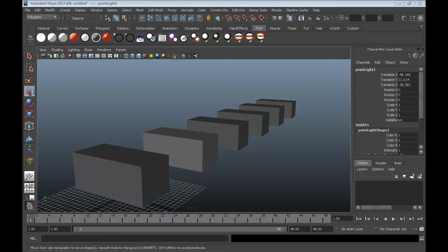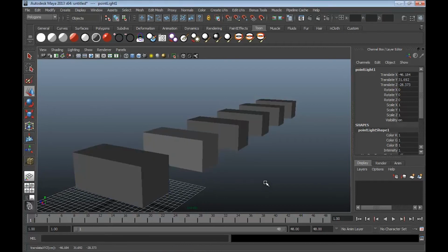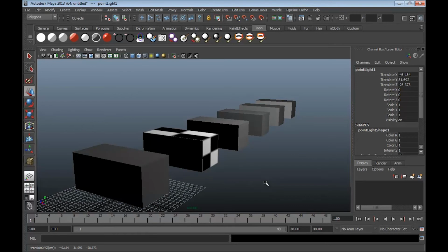When we got done, we had just taken a look at various viewport modes, including wireframe, shaded, textured, and lit, which are attached to 4. If I put focus back on Maya, 4 for wireframe, 5 for shaded, 6 for textured, and 7 for lit.